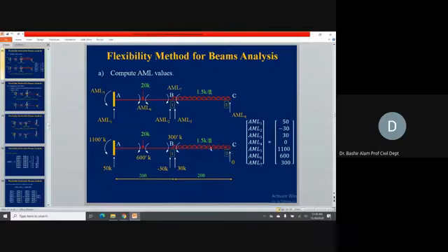The load is traveling towards the support at A, where we have a fixed support. Just to the left of this section, what will be the reaction? It will be 1.5 times 1, so 1.5 kip in the upward direction. Just to the right of this section, which we are taking at 1 foot, and just to the left of that section, it will be 1.5 in the downward direction.